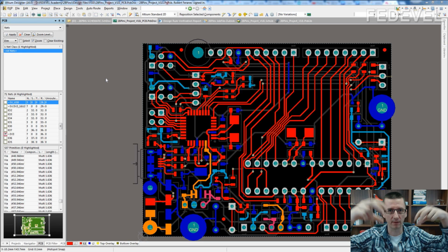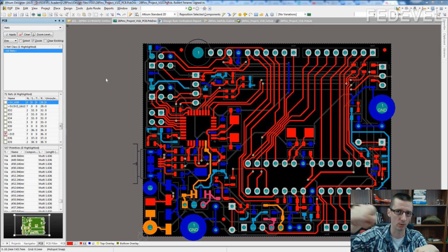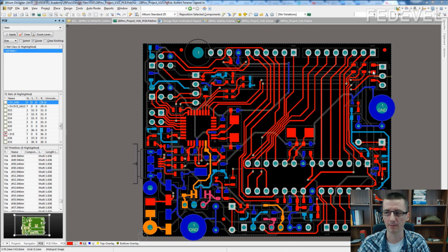When you place the vias first, then you can route around them. If you route the tracks first and then place the vias, you need to reroute what you already did. Here, this was very simple. There is a lot of free space, so we could very easily connect the power by the end of the layout. But as I said, the process of designing this two-layer simple PCB is a little bit different than how you design really complicated PCBs.